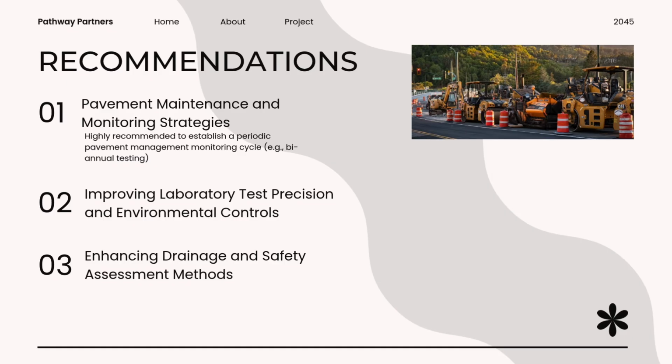And finally, enhancing drainage and safety assessment methods. Visual drainage tracking should be upgraded to digital logging or high-speed video recording to eliminate human reaction lag when timing the outflow meter. This ensures that the water cleared by the macrotexture effectively reaches the roadside drains instead of accumulating into localized ponds during intense monsoon downpours.